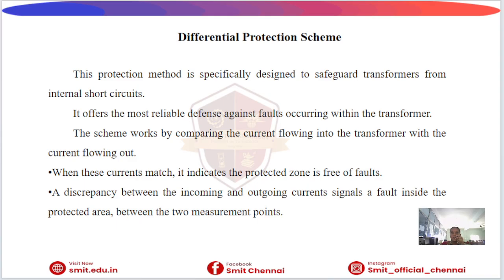Differential protection scheme. Differential protection is used to detect internal faults in transformers. It compares the input and output currents of the transformer. If both currents are equal, the transformer is normal. Otherwise, any difference indicates a fault and trips the system.